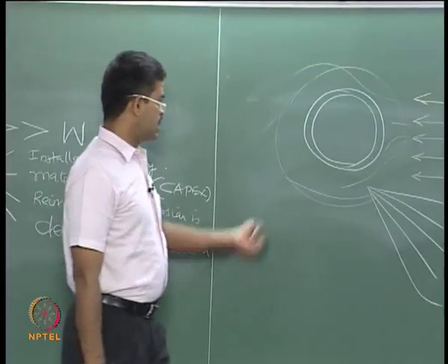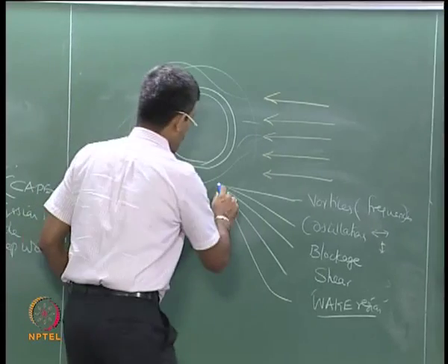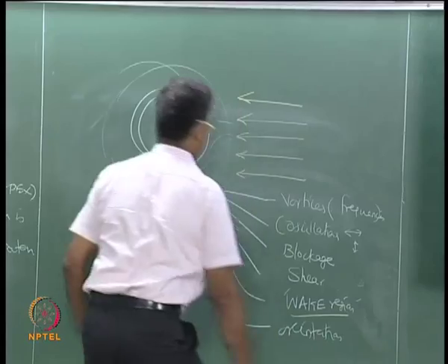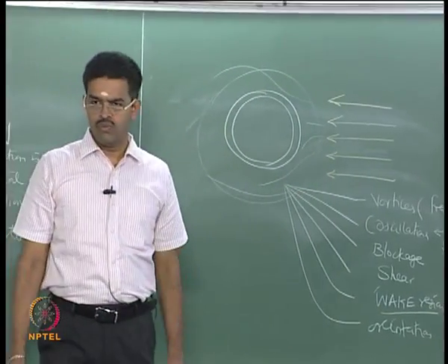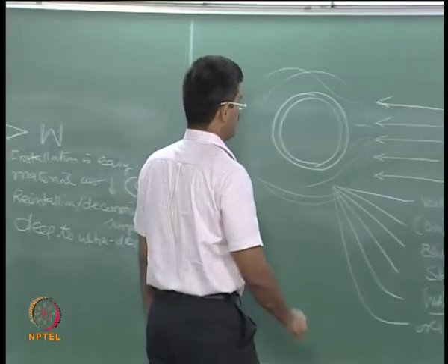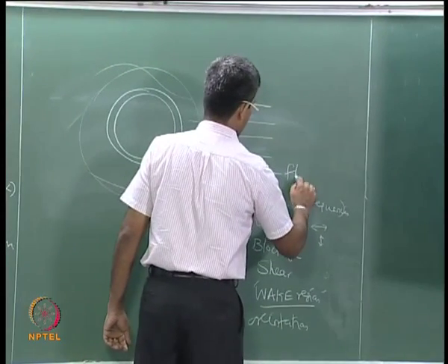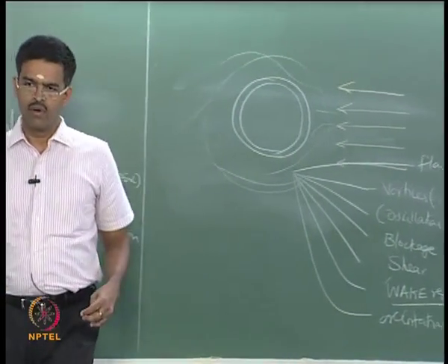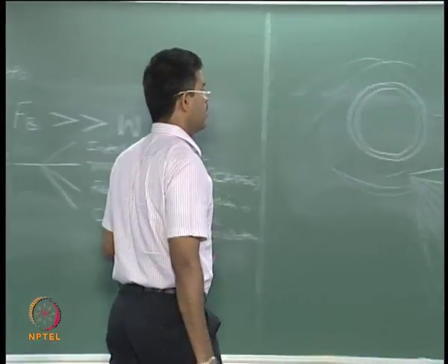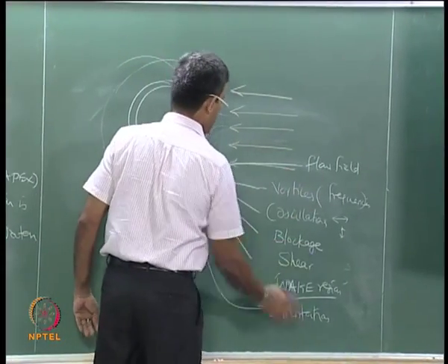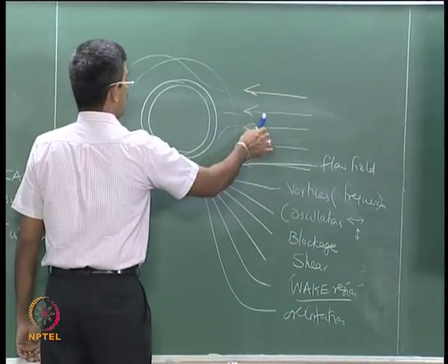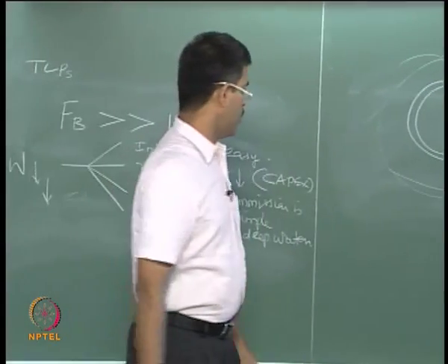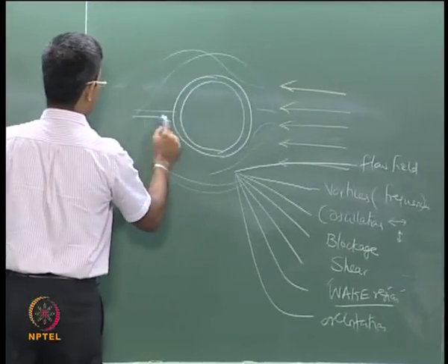So there is the interference in a single cylindrical member, and of course the orientation of the member, whether you place the axis of the member parallel to the flow or normal to the flow, and of course the flow field, whether the flow field is uniform or shear type. Depending upon the variety of factors influencing the flow field on the member, fluid structure interaction becomes interesting and important. And therefore how this affects dynamic analysis is very simple.